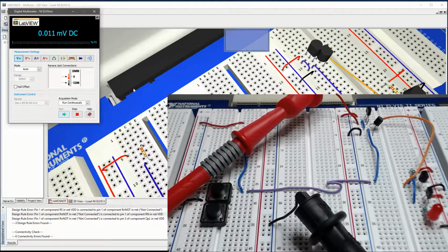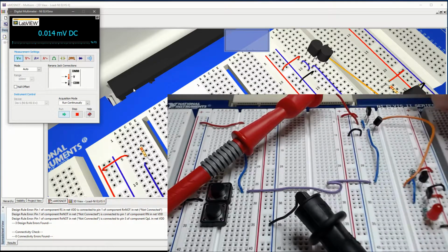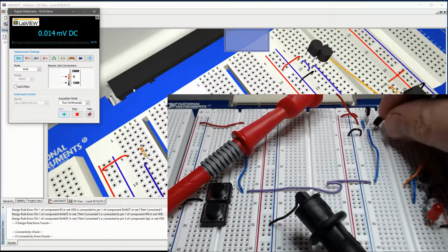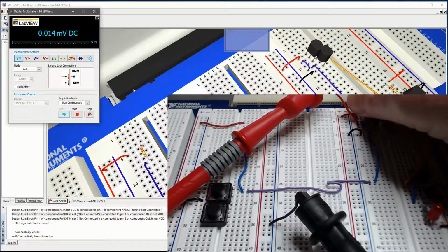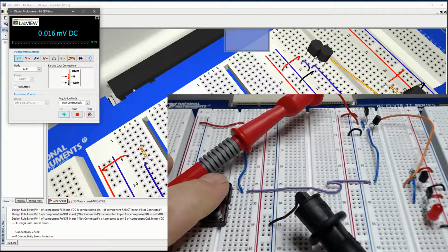Right, the problem was I had my pMOS around the wrong way, and also I had a ground in here that I shouldn't have. I've fixed that now. Also, it was generating a bit of heat, believe it or not. So we now have the correct function.